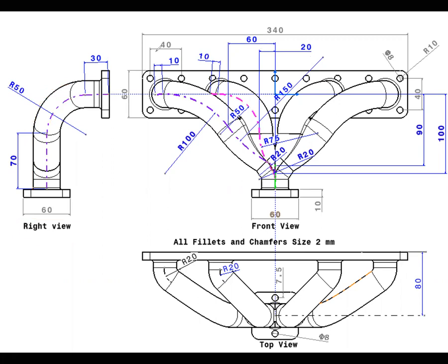But when you see some other projection, suppose there is another pipe projection like this one, the center curve is different, and we have to draw the center of this pipe for the second pipe. But in this case, the center of pipe one and pipe two, when you view from the side, is the same curve. But the front view curve is this one for the second pipe and the remaining two pipes.